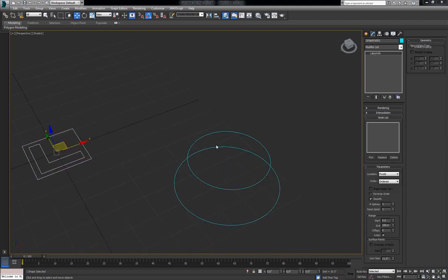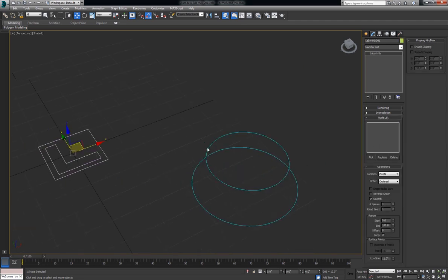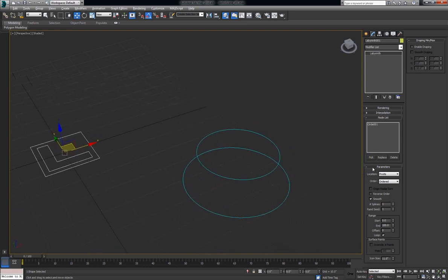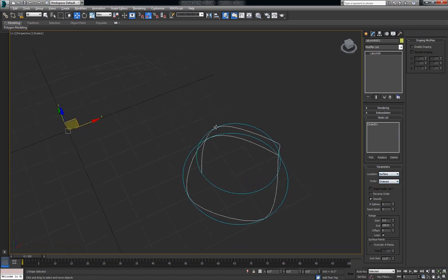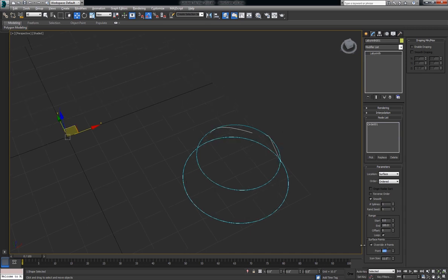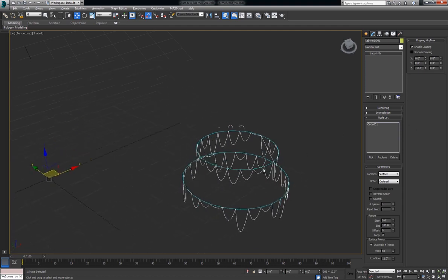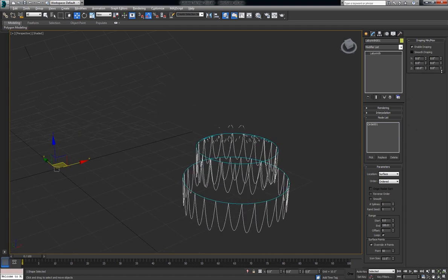So next I'll show you how it works with spline shapes. And this is just one spline set up here. It's just one node. I'll quickly add it to the list and then use surface. And right now it's generating a spline knot for every knot in the spline shape it's generating on. So we can override that. We'll say we'll do 50 points. Turn on draping, and we'll turn off the smooth for the main points and turn on smooth for just the draped points.